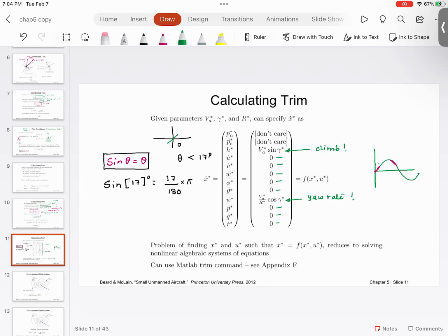Now here is the trick around it. So what you do is you design a controller, and this is the crux of nonlinear control theory, to design a controller so that you push those eigenvalues, you make them so negative, or you make that system so stable that even if there is nonlinearity, the system poles do not cross the imaginary plane.